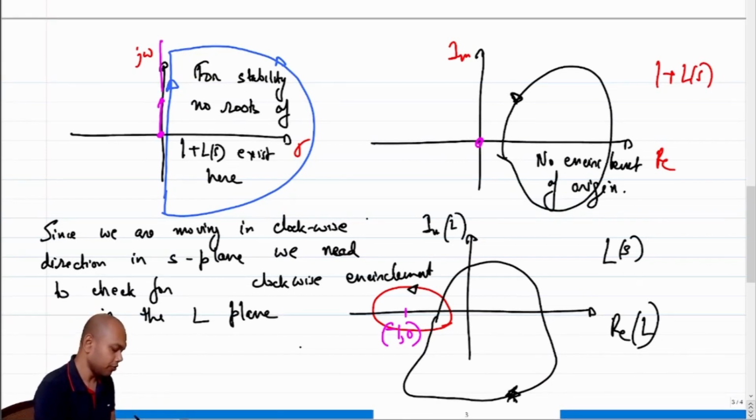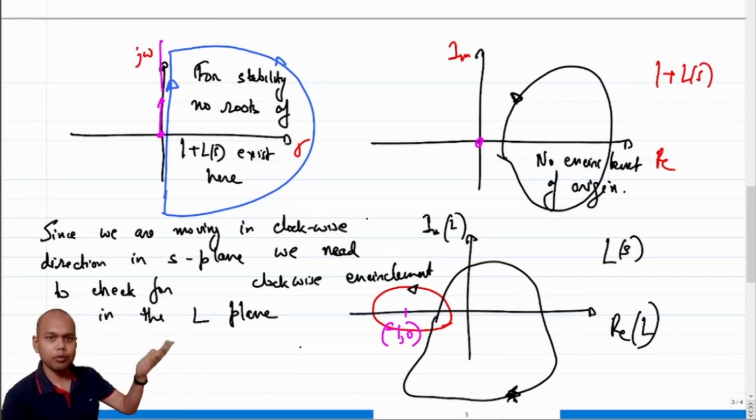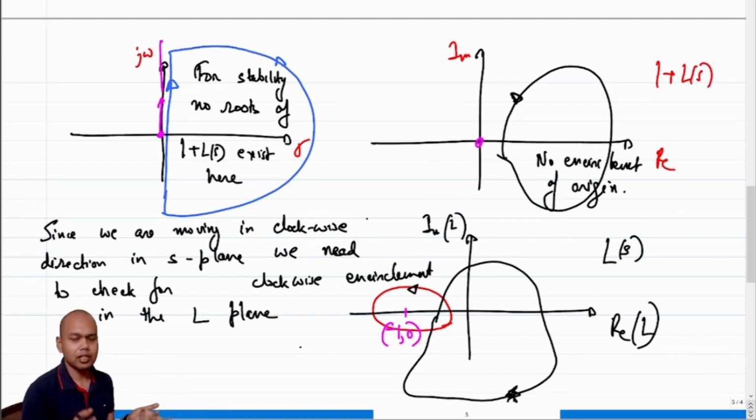We are going all the way to infinity. So what happens to the transfer function in any realistic transfer function when we go omega to infinity? Because in any realistic transfer function, the number of poles is always greater than the number of zeros, but especially it's kind of a low pass transfer function. Eventually everything has to go to zero. So if you go to infinite frequency, the transfer function essentially goes to zero, right?